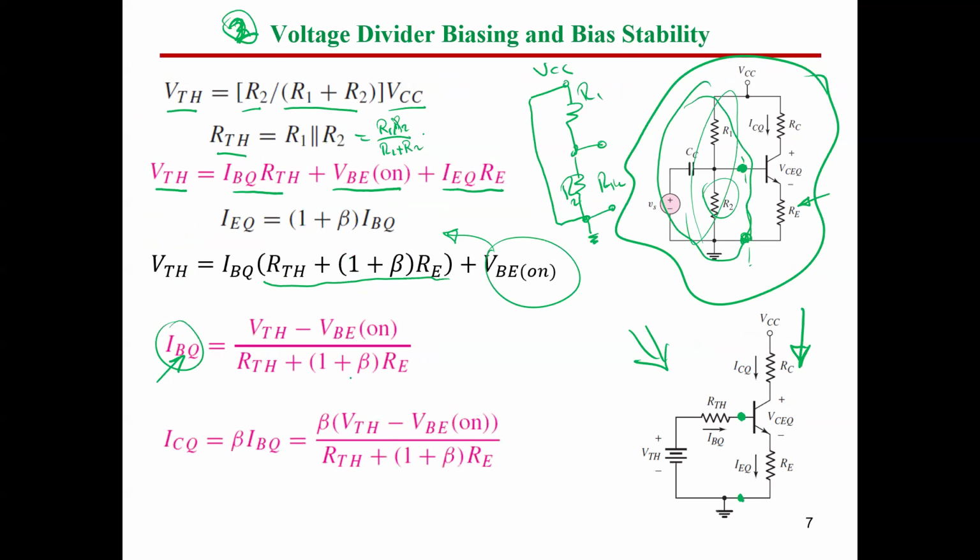So this means you have to change as well the value of IB in this circuit. So with different values of beta, you don't have constant IB. You have to repeat the calculations for all the equations. So you have to calculate IB, you have to calculate IC and VCE. You have to calculate everything here once you need to get the effect of beta. Again, it's just direct substitution in the relation.